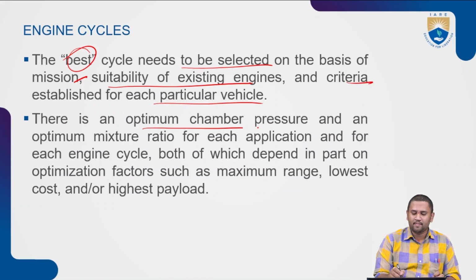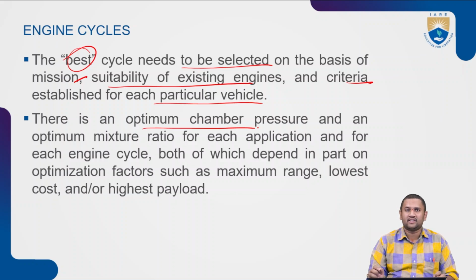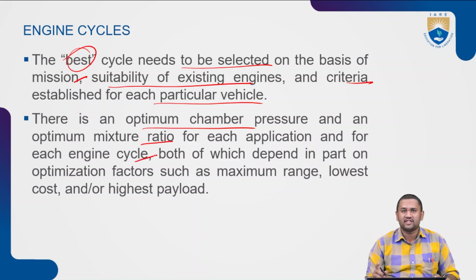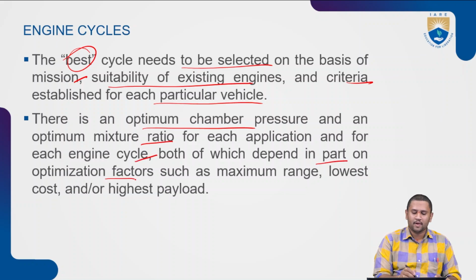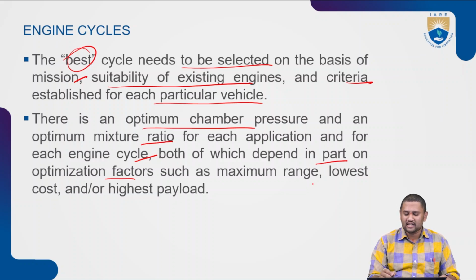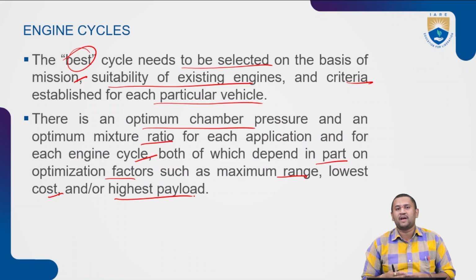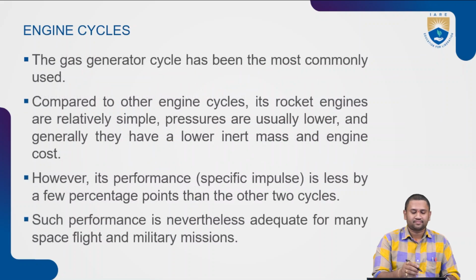There is an optimum chamber pressure and an optimum mixture ratio for each application and for each engine cycle, both of which depend in part on the optimization factors, so considering the maximum range, the lowest cost, as well as the highest payload carrying capacity.